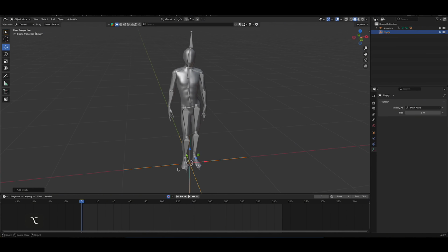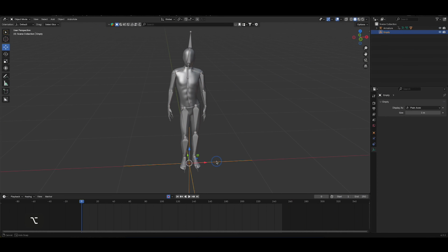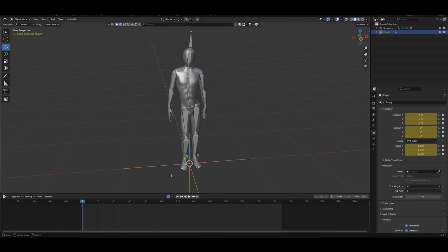And we're going to create animation of the rotation for the pivot point, but not for the armature. So let's select the pivot point first. To animate that, first, I'm going to go into the very first keyframe again. Here, I'm going to press I in order to save in memory all of the possible keyframes inside of the pivot object. Then I'm going to move it to the end of the timeline, the visible timeline, which is very important. I'm going to change the Z-axis rotation.